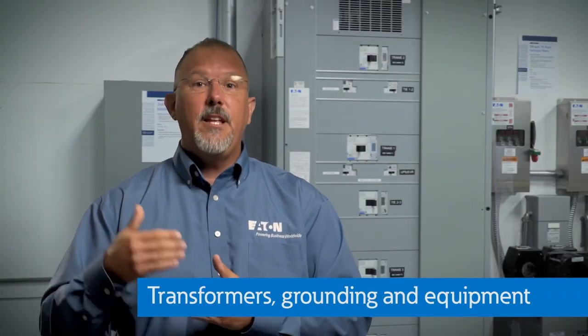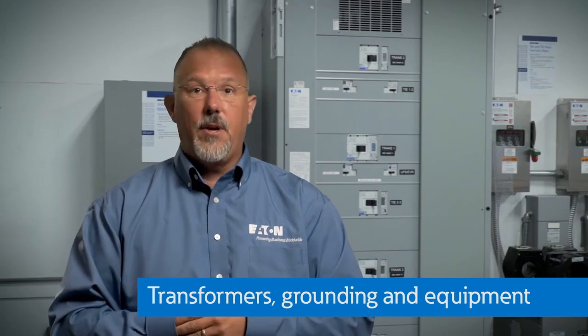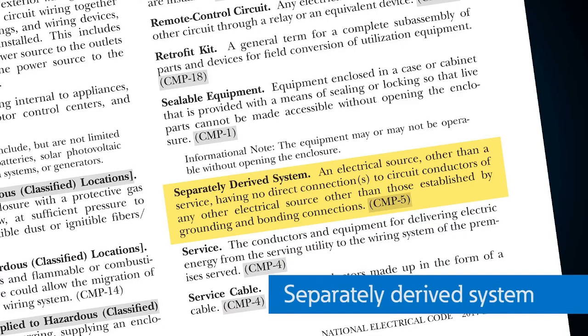Now we're going to move over to transformers for grounding and bonding inside of transformers. When we move into a transformer, we're talking more like in a separately derived system. This is your electrical source other than a service having no direct connections to circuit conductors of any other electrical source other than those established by grounding and bonding connections. That's your separately derived source. So let's talk about that transformer.